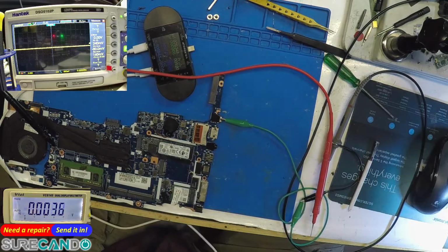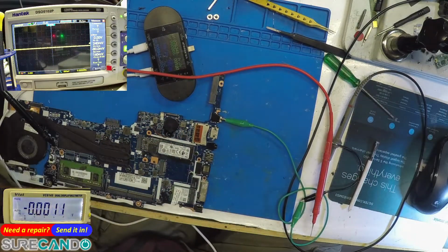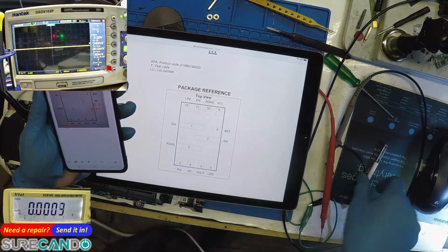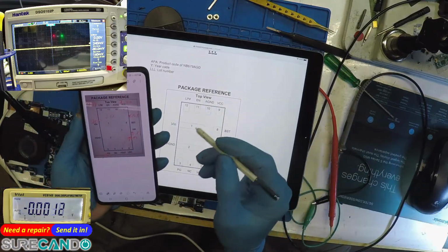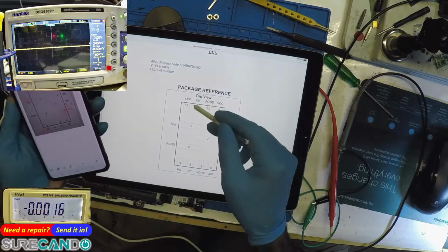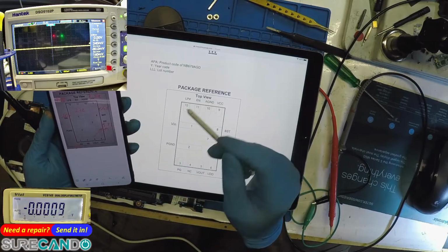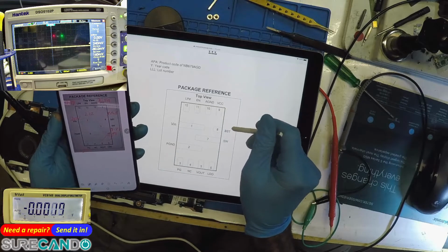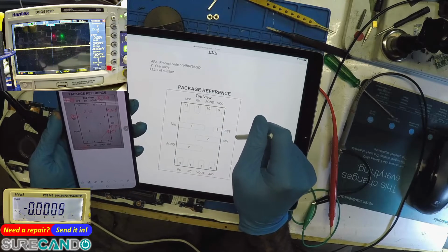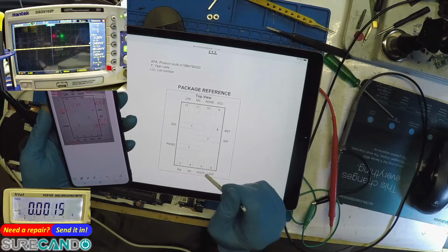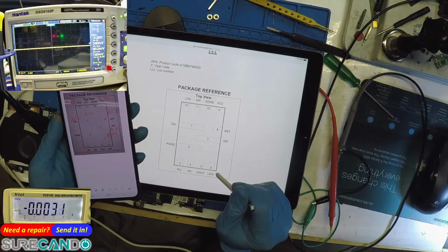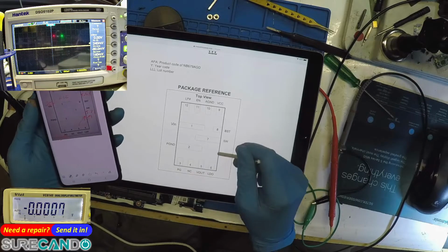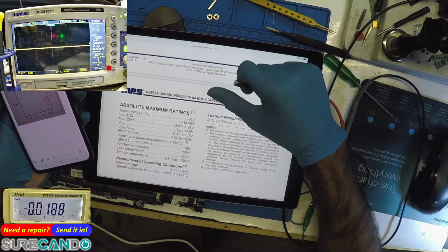Cut the power. I mean, iPad you can write as well. I haven't got that feature, pen. So LP we got 4.88. Enable we got 2.12, 3.59 on VCC, 8.58 on BST. Switch, voltage out, LDO all 5.27. And then 1.34 in the power good. Okay, let's have a look.